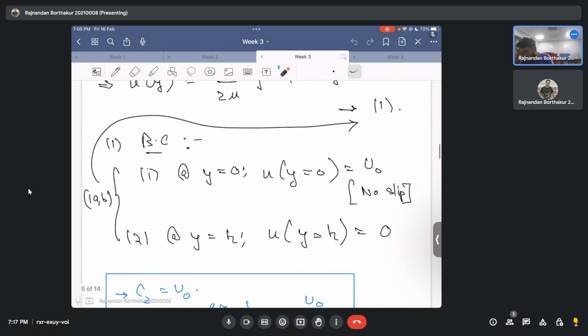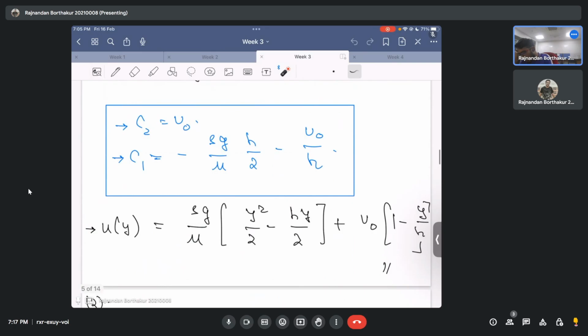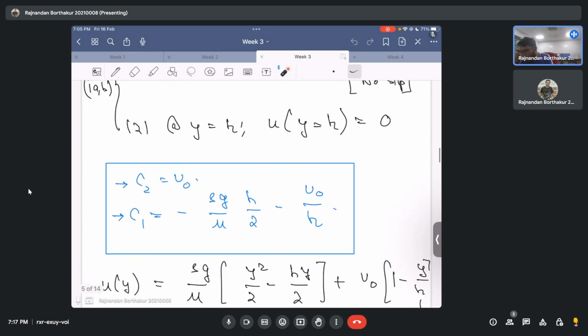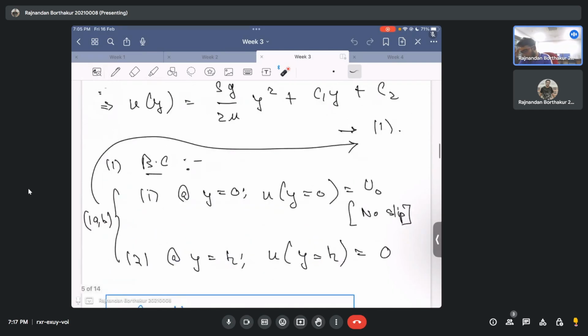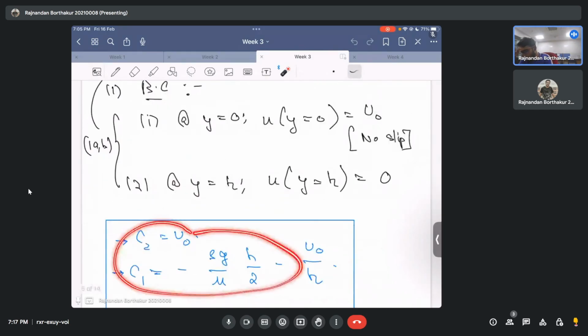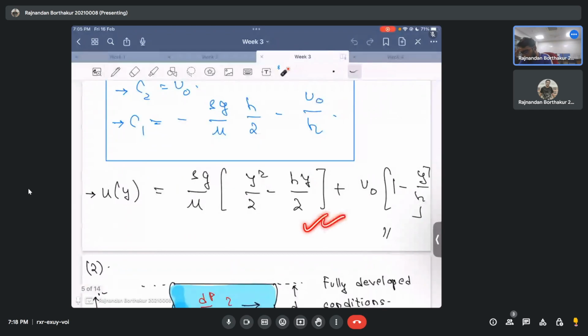And we found out that the velocity profile was something like this. Keeping in mind that the boundary condition at the surface of the belt is the belt velocity itself, and when you move far away from the belt, the fluid velocity diminishes to zero, which are used to evaluate the constants C1 and C2. And then we got the velocity profile.